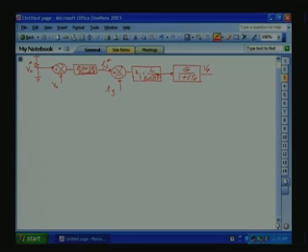So, that will be removed as a disturbance input, and then the closed loop block diagram will be 1 by SL, then you have this one, current feedback Ki comes here. This is our current loop. Now, how do we design the voltage loop?